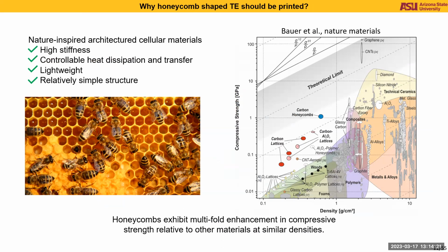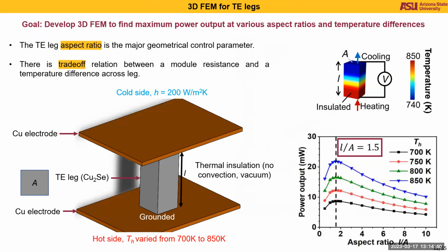So we can take inspiration from these architectures and try to print the thermoelectric legs as a honeycomb structure. But we have to understand what's the underlying physics behind it if we are getting better properties using this architecture. So for that purpose, we developed a three-dimensional finite element model using the multiphysics of thermal and electric current modules. The most important parameter in a thermoelectric leg is the aspect ratio, which is the ratio of leg